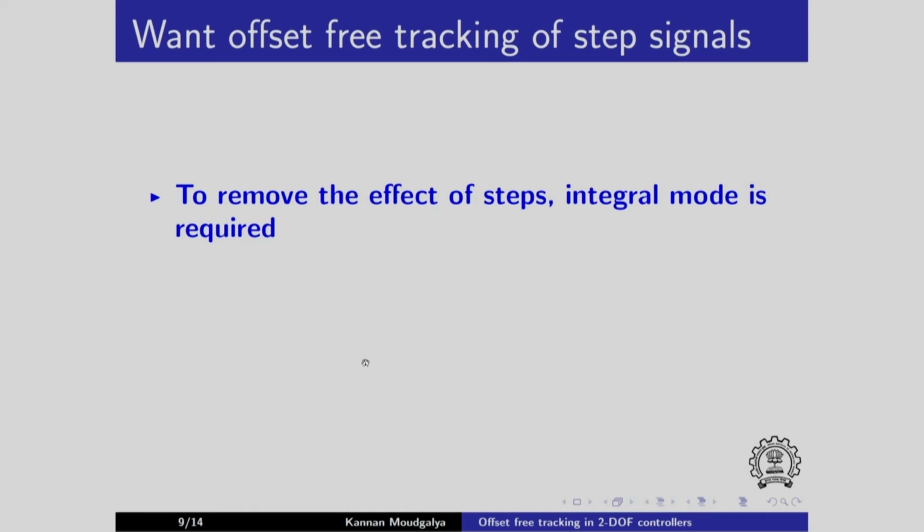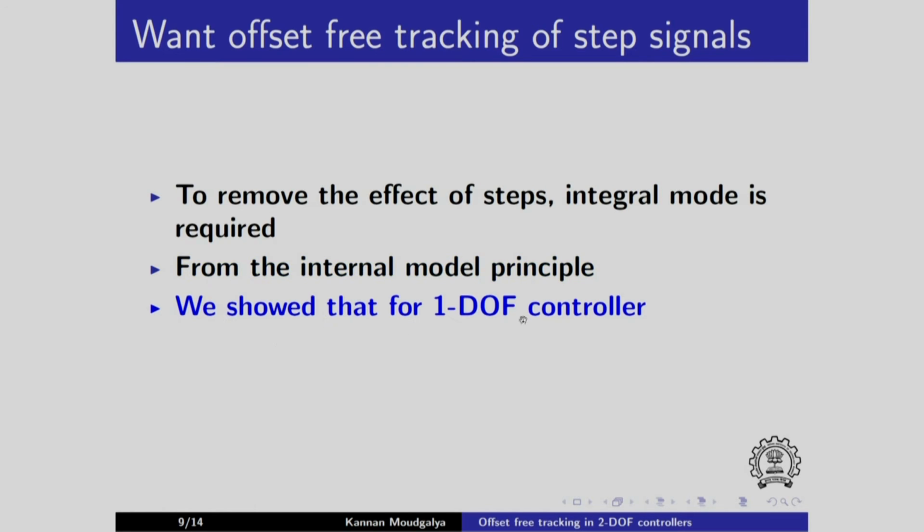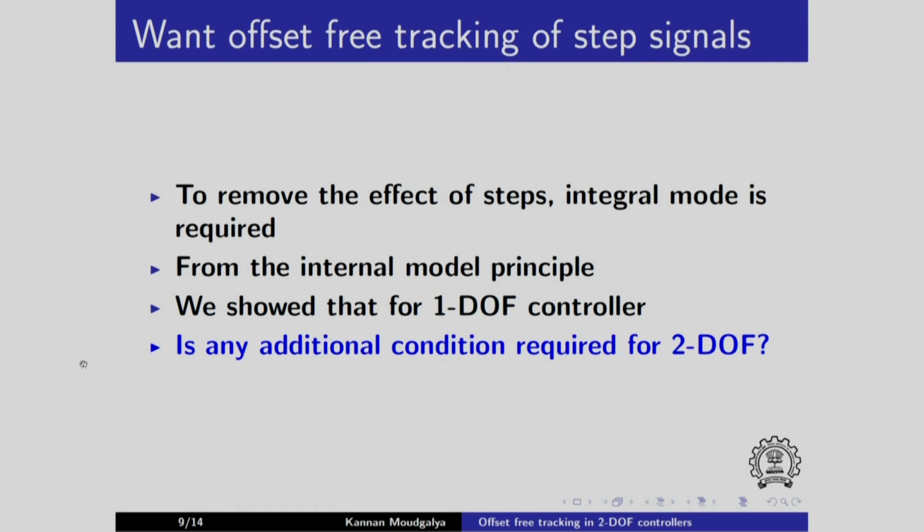We want to track step signals without any offset. We know that in order to remove the effect of steps, integral mode is required. We know this from the internal model principle that we studied earlier. We showed that for 1 DOF controller. Do we need any additional condition for 2 DOF controllers? That is what we want to answer now.